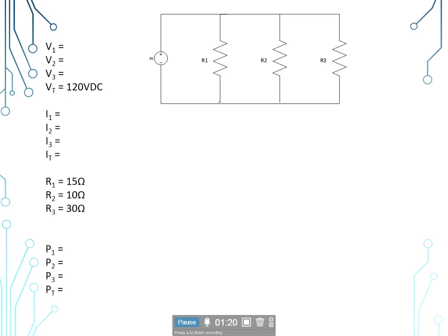Now to get started, we're going to have to find the total resistance of this, and for the total resistance, we can use 3 different methods to do it. The first one is resistors of equal value, where each branch would have to be exactly the same resistance, and you'd take the resistance of one branch and divide it by the number of branches. We can't use that here because we have 3 different values for our branch resistances.